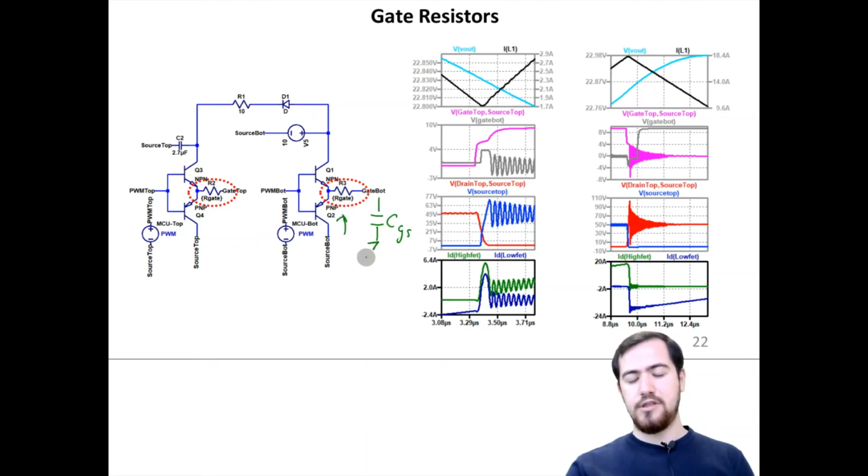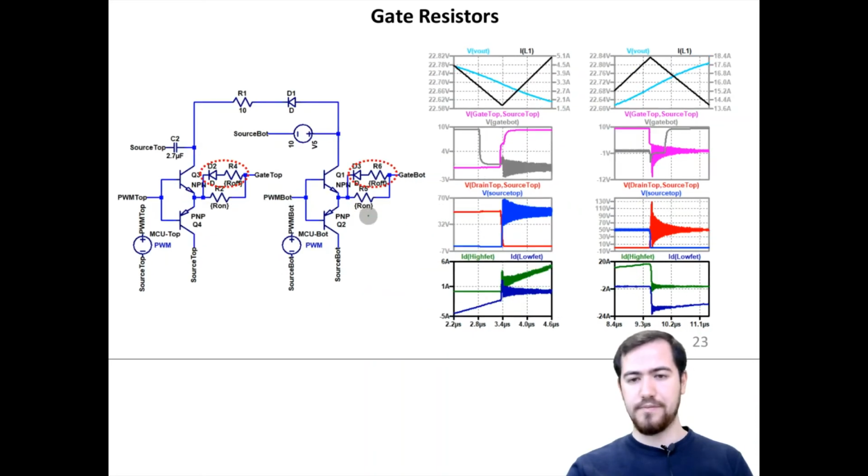So in this way, you are increasing the conductivity of the MOSFET slowly, or reducing the conductivity of the MOSFET slowly, which means that you are turning on or turning off this switch over longer periods. As a result, we are observing a voltage reduction. Now it is as seen below the 100 volts for the low side or the high side switch as well. We can solve this problem.